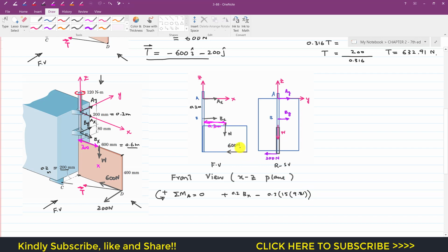And now this 600 Newton component of that tension T is going to produce the clockwise moment about point A as well. So I will write minus 600, and the perpendicular distance of this 600 Newton force from that point A is this distance. Let me write, this distance is 80, or we can say that this is 0.08. Remember, 80 divided by 1000 will give us 0.08 meters.